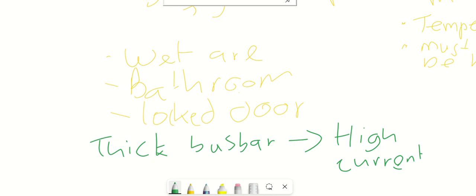When you try raising it up, it falls again. So that's a miniature circuit breaker. It automatically switches off when there is a disturbance, either overcurrent or short circuits. It will automatically shut down the whole system. Okay, so that you must also know.